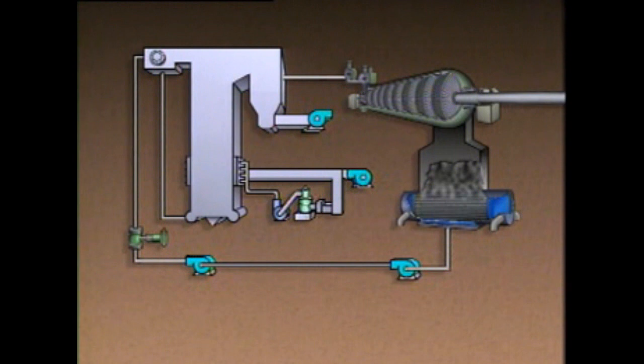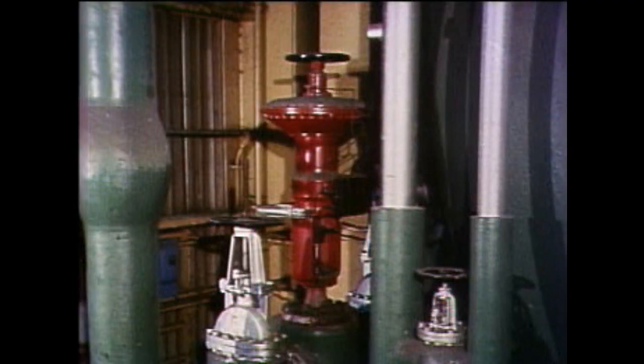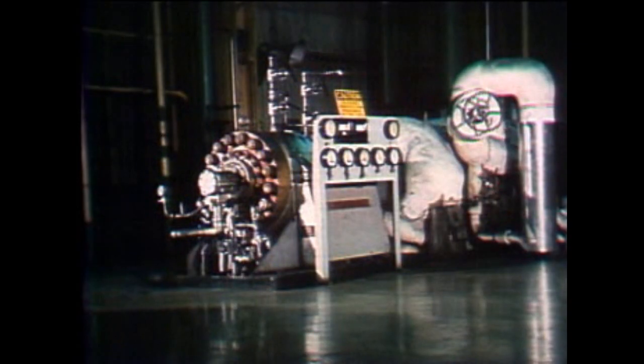In this system, feed water flow to the boiler is controlled by a valve in the feed water line going to the boiler. The feed water control valves are opened and closed to match feed water flow with steam flow. In some plants, this control is accomplished by varying the speed of the feed water pump. Other plants use a combination of both methods. Regardless of which method is used, the important point to remember is that steam flow and feed water flow must be controlled so that they're balanced.